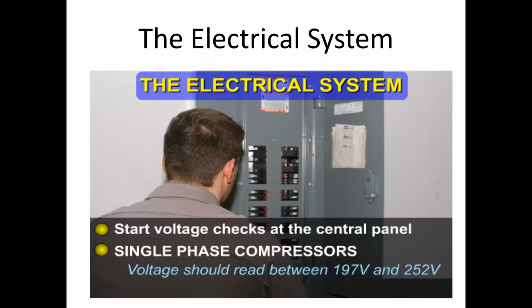But if you're running 196 volts, your current is going to be too high, right? So that's going to cause issues. If you're running 260 volts, your voltage is going to be too high for that unit. You're going to overstress those components.